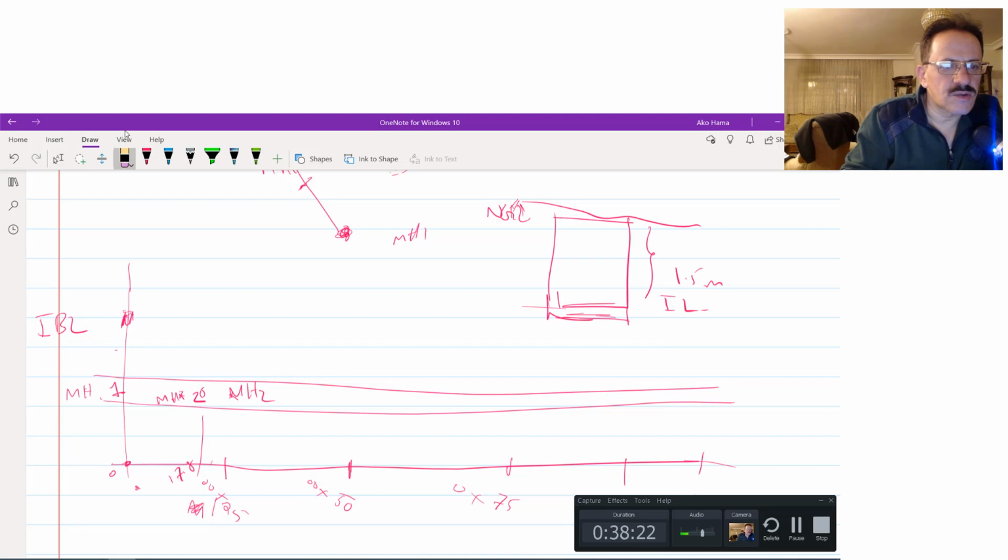Okay, the first invert level is 1.5 deep. So you have to have the level here. Let me say this is 106. If the natural ground level is 106, how much will be the bed invert level?